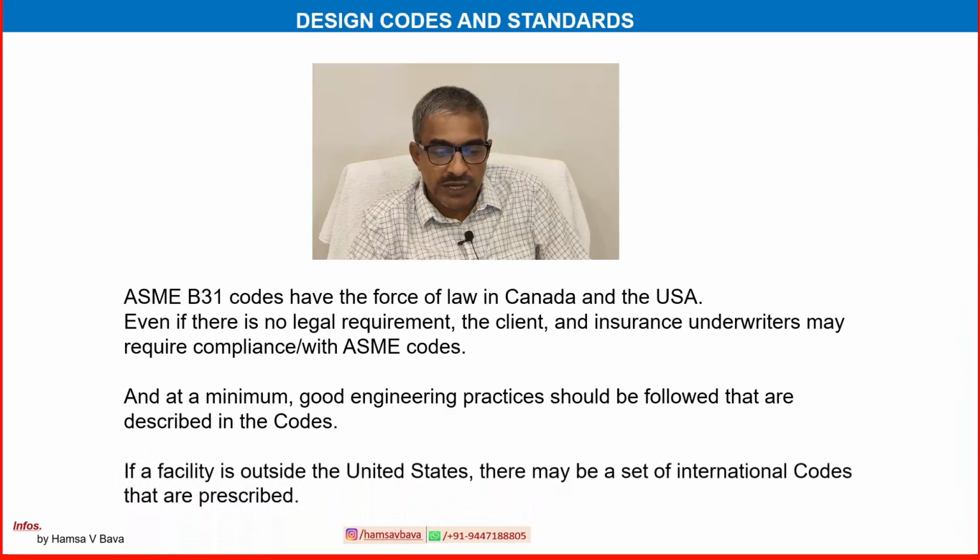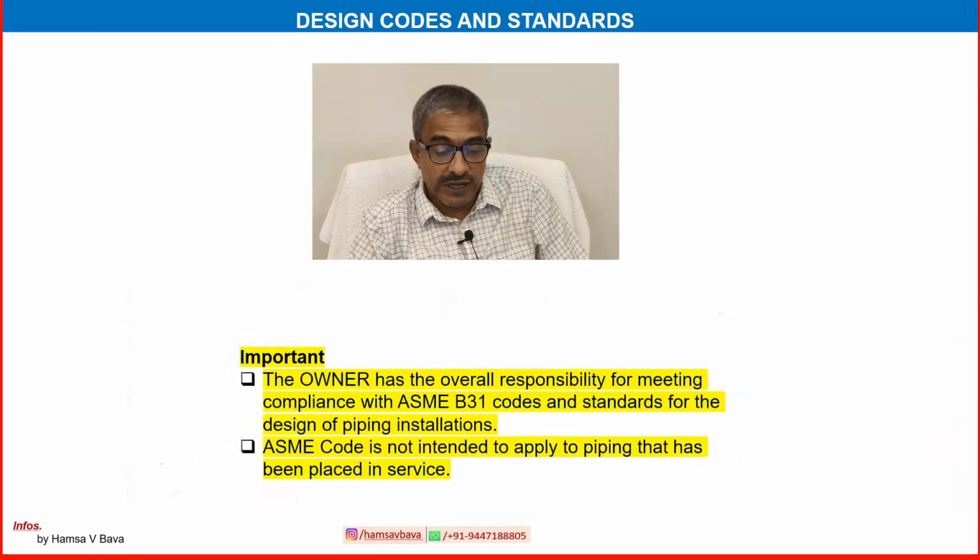If a facility is outside the United States, there may be a set of international codes that are prescribed. Important information: the owner has overall responsibility for meeting compliance with the ASME B31 codes and standards for the design of piping installation. The ASME code is not intended to apply to piping that has been placed in service.